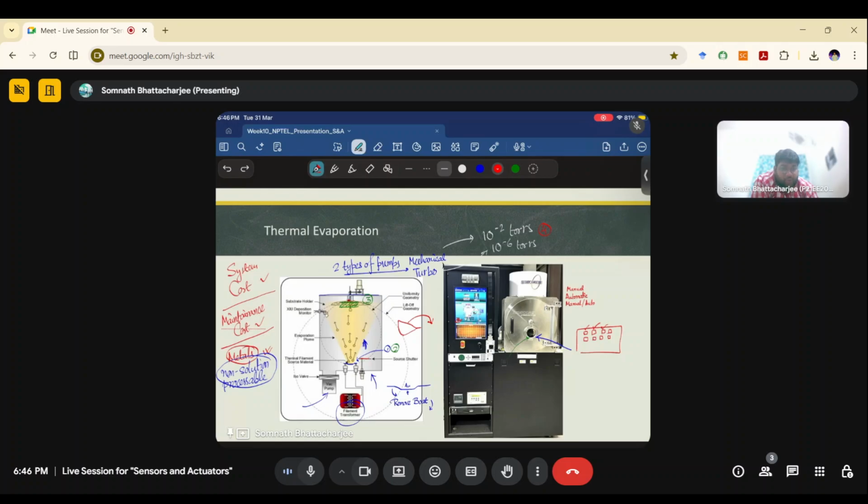If you need a specific deposition rate, a very specific uniformity, and if you need to calculate your thickness directly, like we have already learned about different measuring techniques, let's say profilometry, ellipsometry, and these kinds of things, you will have to utilize this shutter. After achieving a constant deposition rate, we'll change the position of this shutter, and based on that the deposition will start.